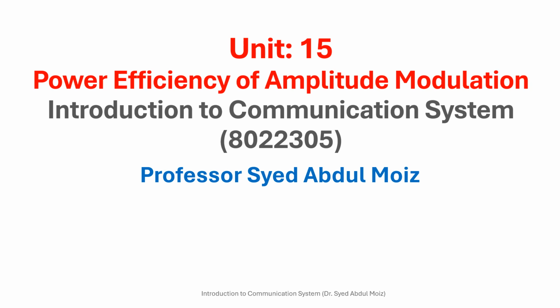Under these conditions, the power efficiency of AM reaches a theoretical maximum of 33.33%, with the remaining power consumed by the carrier. This inherent limitation makes AM less power efficient compared to other modulation techniques such as single sideband or frequency modulation. In this Unit 15, we will discuss the details and derive the equation for the power efficiency of amplitude modulation.